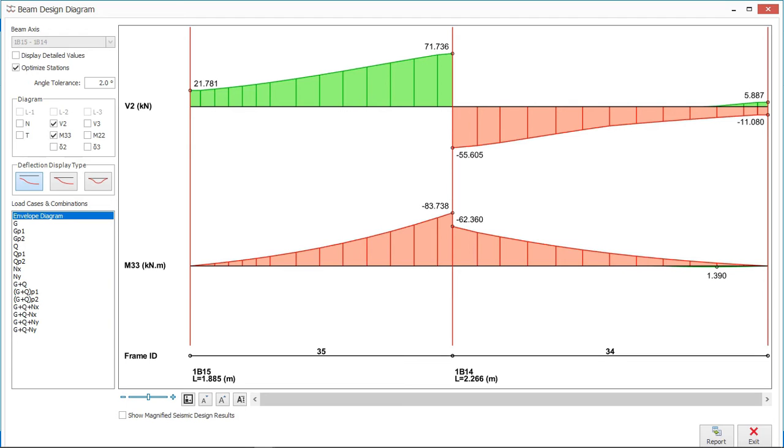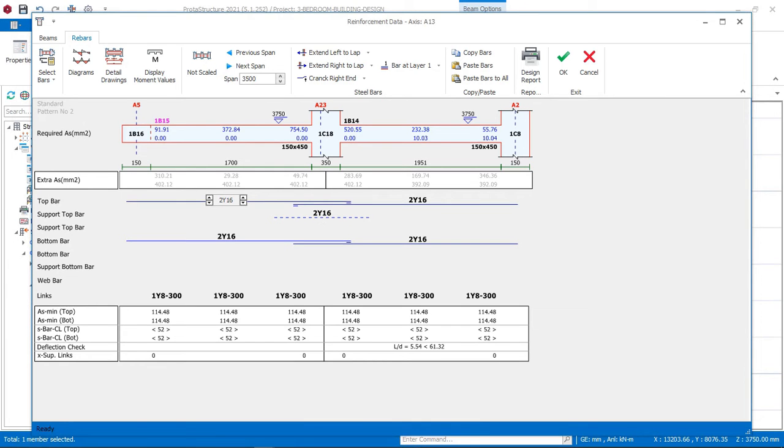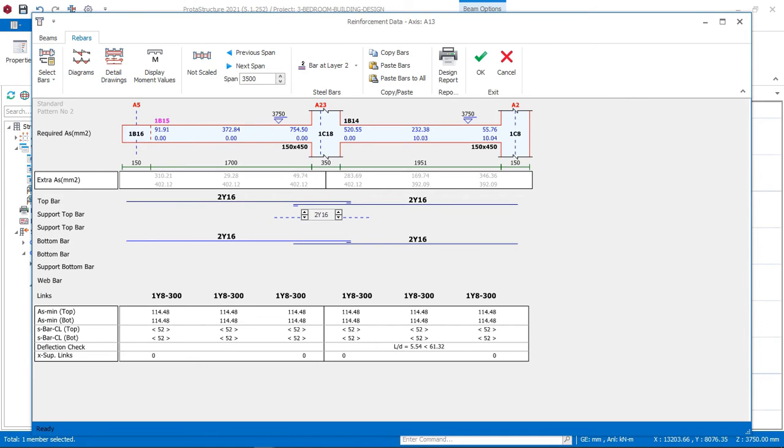You can see that we have a higher value of top. We can see there, this is for shear force. And I can now see that we have a higher value of our top moment here. You can see that right now. So because of that, I'll go ahead and make here to be 3. Now because of 3, it's trying to lessen the space where the concrete is going to pass through the reinforcement, so I'll reduce here to be 2. During the structural detailing, I'll make these 2 support reinforcement here able to pass through this span.